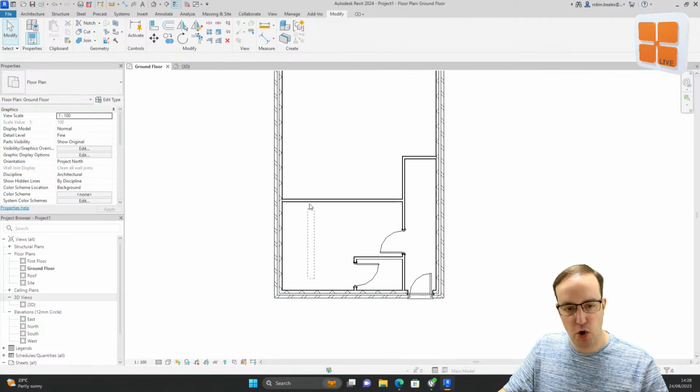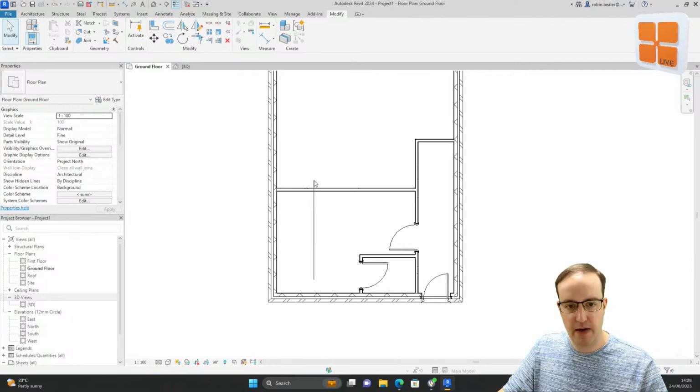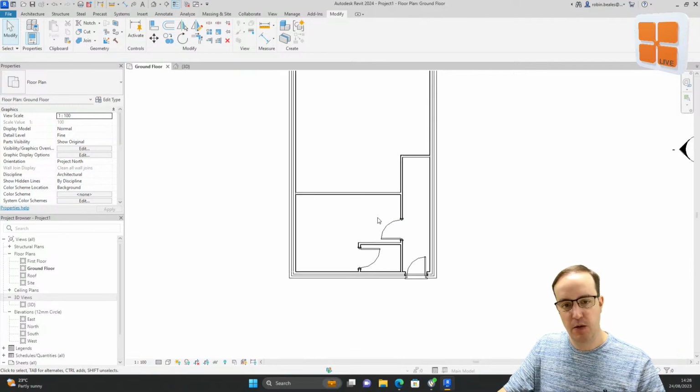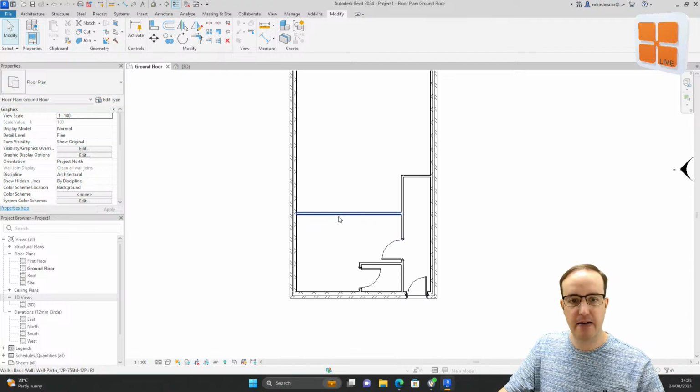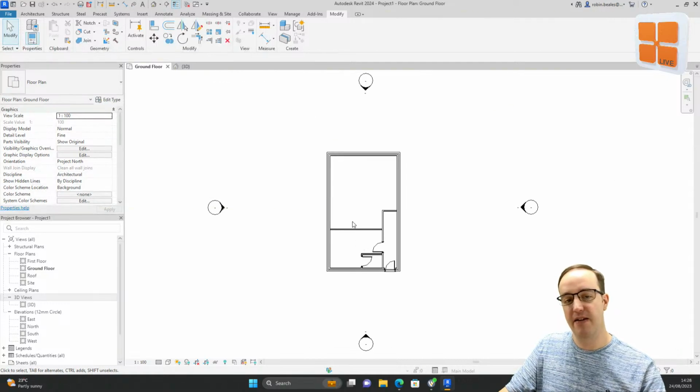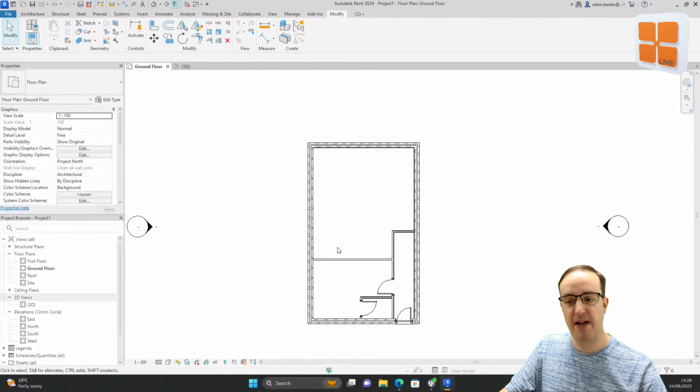I want to have a look at this wall here so I can have maybe a nice opening so that we've got a bit of a flowing space between here and here. So let's place down a section. The great thing about Revit is because it's live, we can choose to create views, create sections, create elevations whenever we want one. So I want to look at this wall.